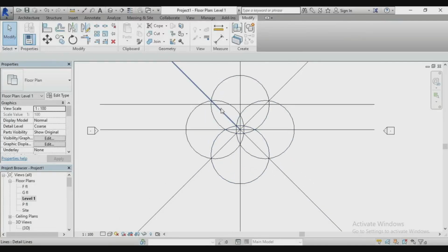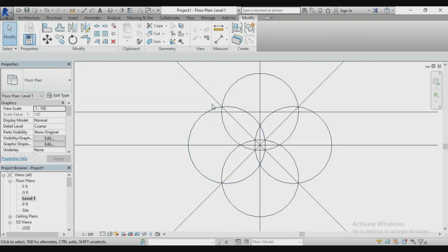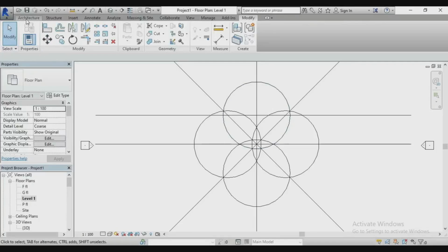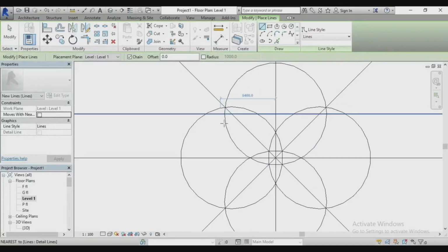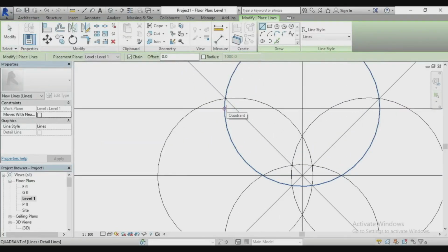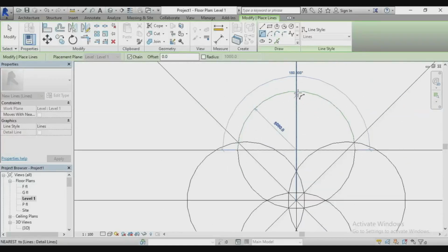I think we have a guide, so we'll try to create the profile for one of these components using modeling lines, LI. So modeling line, pick a modeling line and try to draw an arc along half of that circle we created earlier. Ensure you pick the start, end and radius arc. You can see, yeah, that's my radius, which is 5 meters.